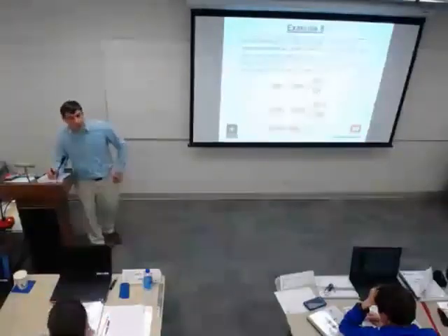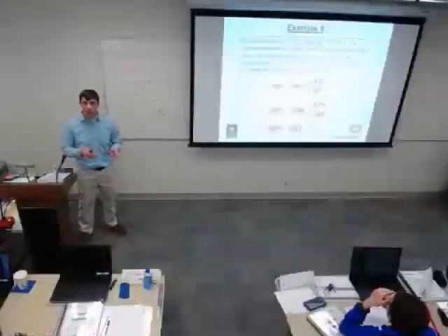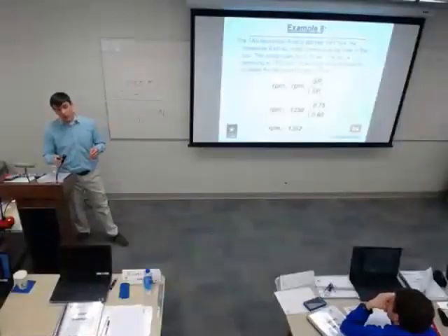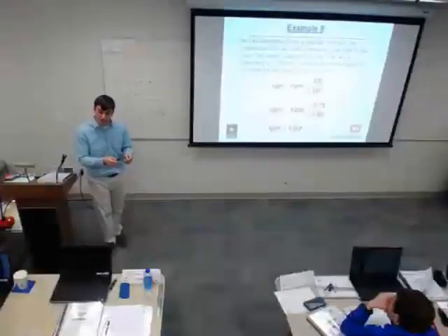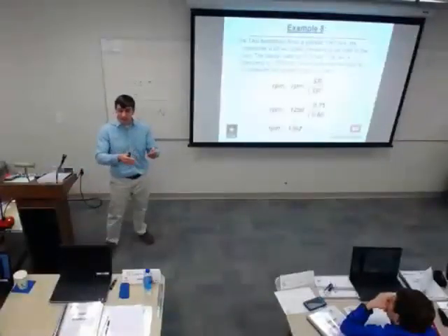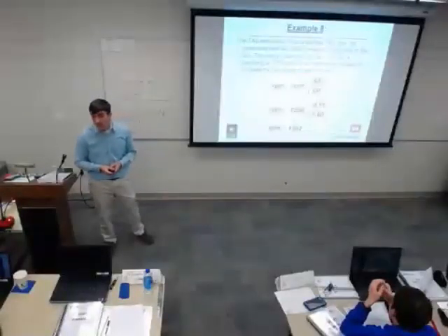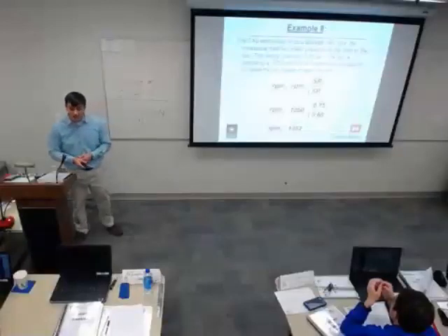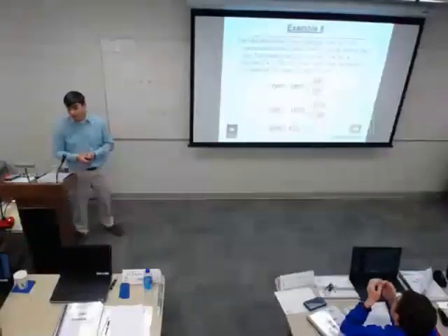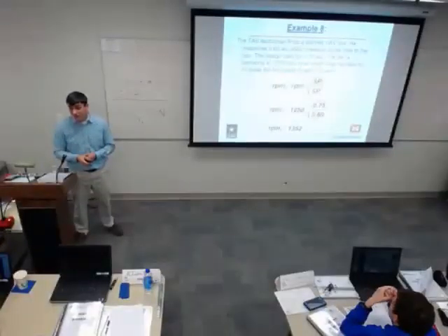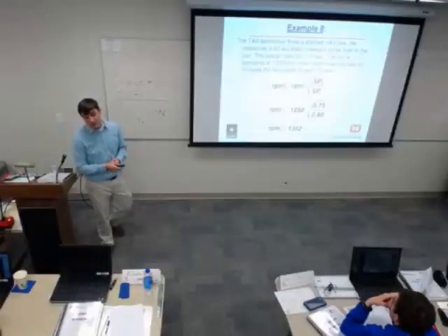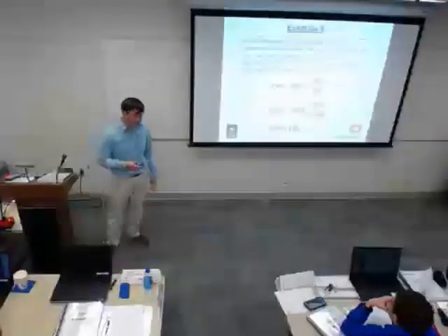Correct. So I would want to ask the question, why am I needing to do this? That's where the information about the static pressure profile comes in. At this point, I'm going to look at whether I have any excess resistance that I wasn't expecting anywhere through my system. It could very well be, like on a project we have right now, that our designer busted and all our ducts were undersized. May not be the TAB contractor's problem. So keep that in mind too.